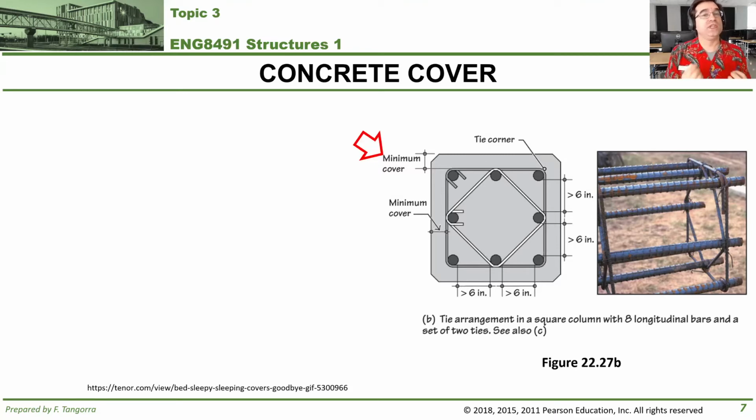And because concrete is designed, for the most part, to be somewhat porous, water can go through it and carry salt with it, but it can also get on top of that reinforcing steel that's close to the surface. If that happens often enough, you can get rusting of the steel. And when rusting happens, a chemical reaction gets the rebar to expand and crack the concrete.